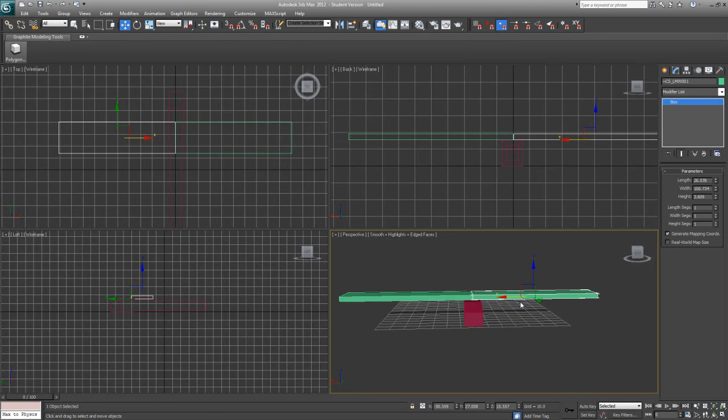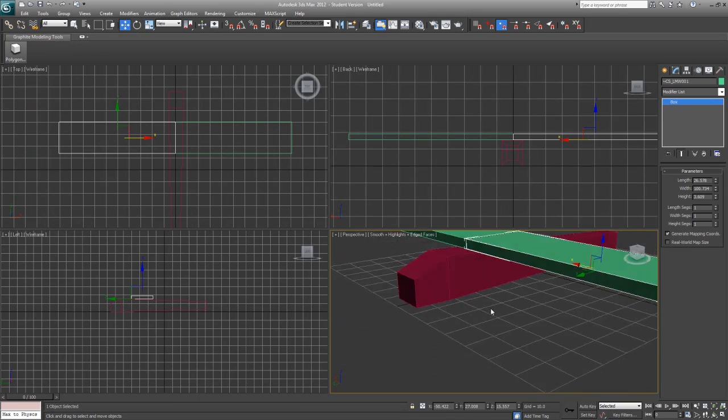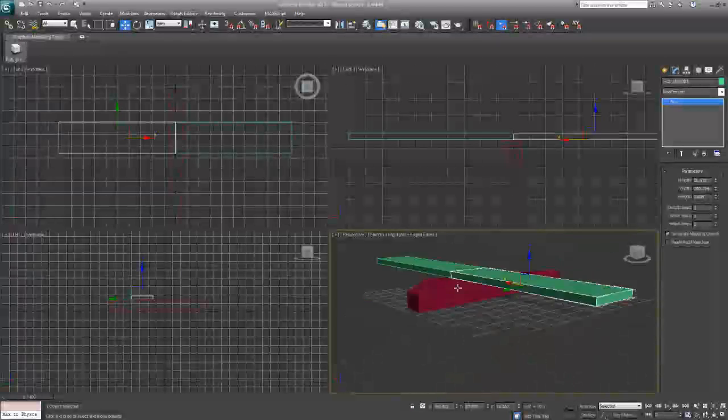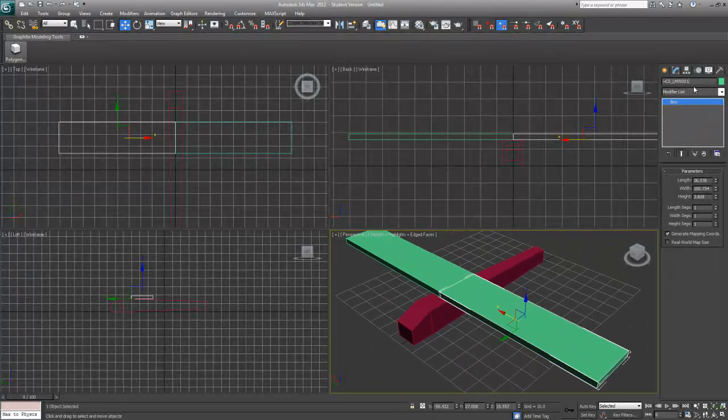Well, there's better ways to do this, obviously, more advanced ways to do this once you get used to the program, but like I said, this isn't about being exact or pretty in any way. You can see that a copy is going to be named the same as the part it was made from, with 001 concatenated to the end. So we need to get rid of that, and we need to now get rid of the L, and now we need it to be RMW, right main wing.